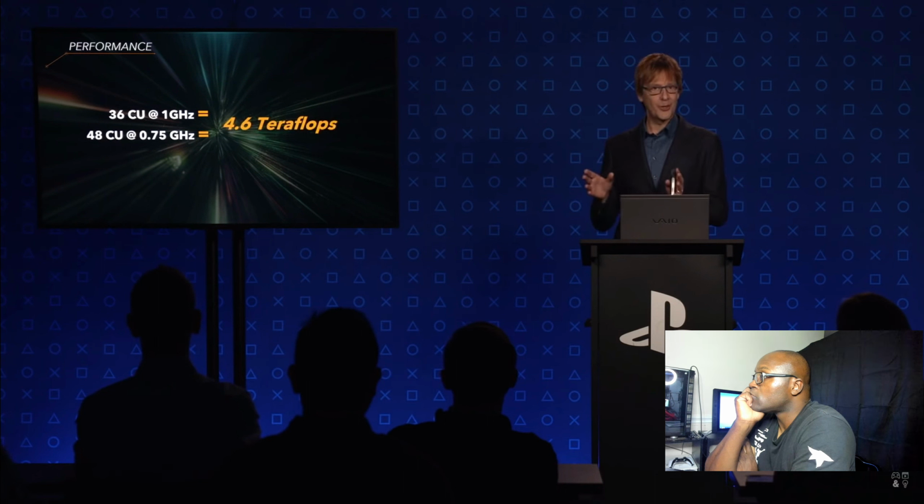But actually, the performance is noticeably different because teraflops is defined as the computational capability of the vector ALU. That's just one part of the GPU. There are a lot of other units. And those other units all run faster when the GPU frequency is higher. At 33% higher frequency, rasterization goes 33% faster. Processing the command buffer goes that much faster. The L2 and other caches have that much higher bandwidth, and so on.